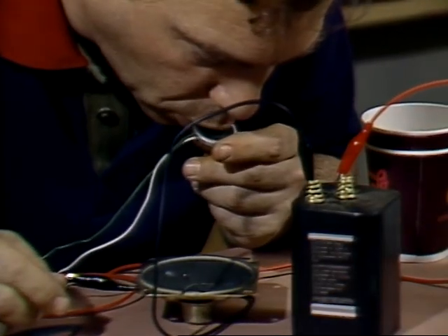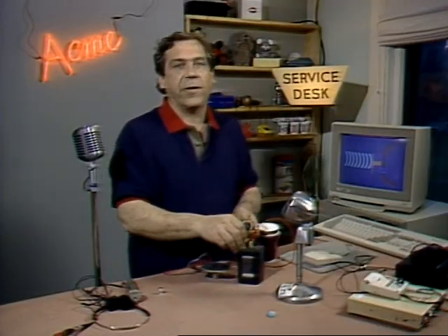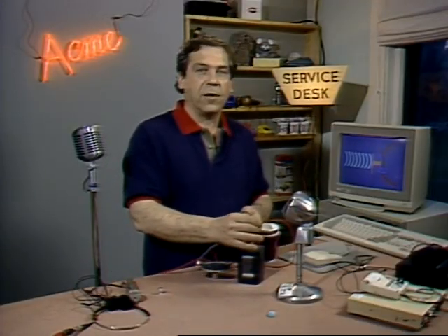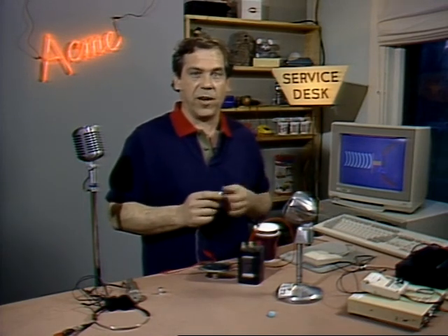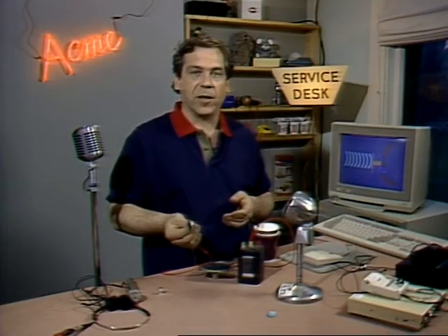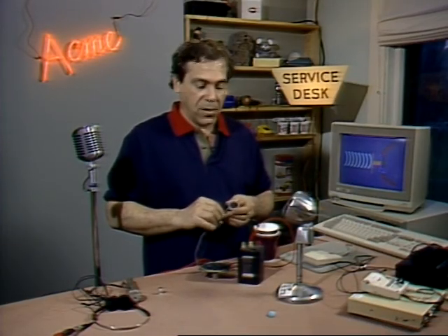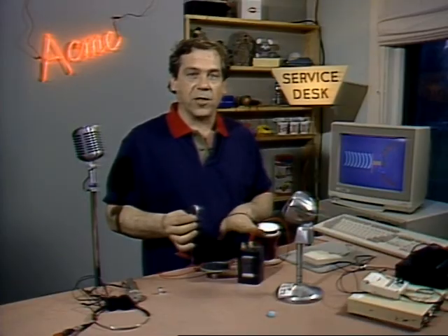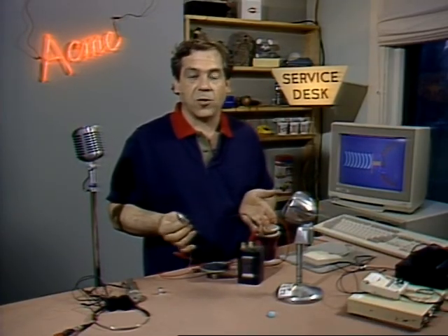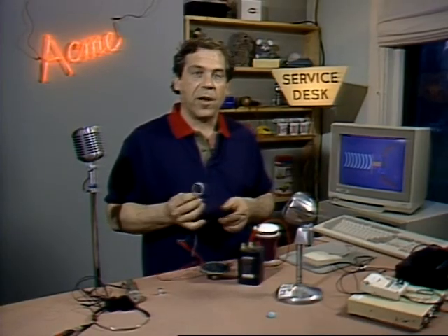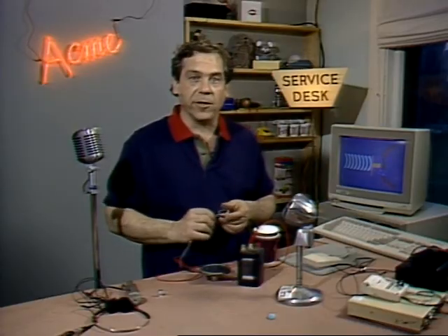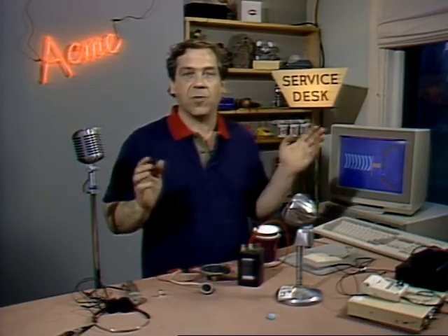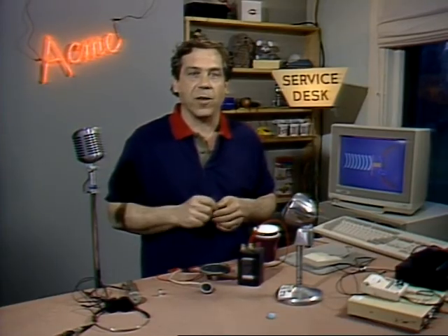Hello? Hello? The carbon microphone has a couple of drawbacks. The sound waves are forced to do a considerable amount of work, squeezing those grains. This has some mechanical implications that affect its sound. And since it operates by wobbling an external current, it requires a source of external current. Early carbon microphones also required a periodic whack to loosen the grains. This ushered a century of people tapping microphones before they spoke into them, and the tradition continues.